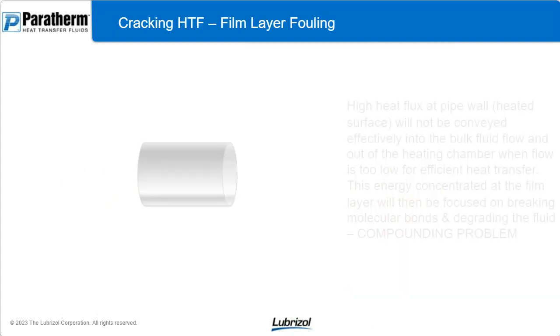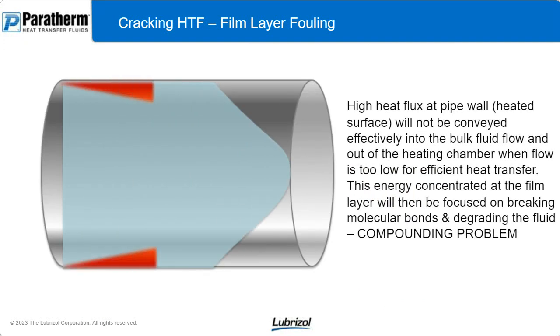Why is that the case? Well, that high heat flux, that high heat energy concentration at the pipe wall, at the heated surface, is not going to be conveyed into the fluid itself. It's not going to leave the chamber, and the flow is not going to be efficient for heat transfer. We talked about this earlier. Heat transfer isn't necessarily about energy efficiency. It's not about saving on energy costs and waste heat and all that.